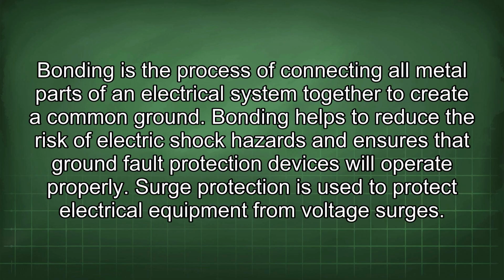Bonding is the process of connecting all metal parts of an electrical system together to create a common ground. Bonding helps to reduce the risk of electric shock hazards and ensures that ground fault protection devices will operate properly.